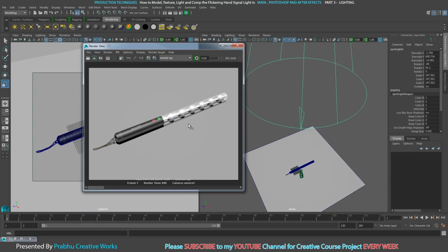So this is a dark scene because I want to show my LED glow effect over here. That means you want to set the key light to a very minimum amount, and then by default the shadow will be enabled in the latest versions. See here, it is 2016. So in 2016 the shadows are enabled by default in all lights. So I want to disable the shadow and reduce my key light intensity.